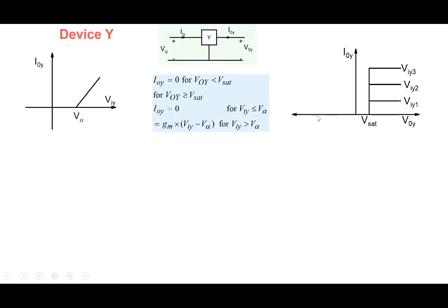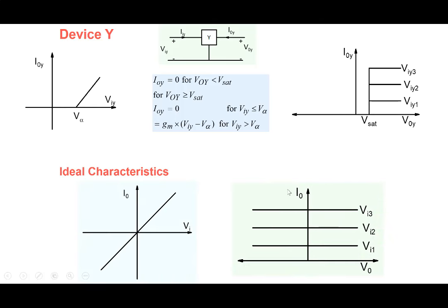And in the negative direction also, the current is zero here. Remember, in an ideal transistor, I naught is independent of V naught and is of this particular nature. So we have two non-idealities: one which was present earlier also, and which we know how to take care of, but we have an additional non-ideality in the output current versus output voltage here.